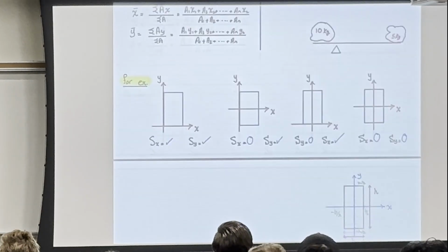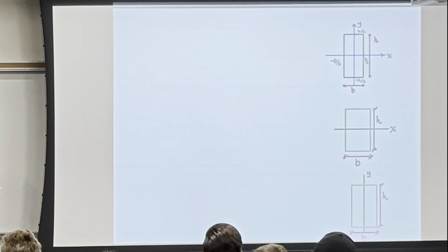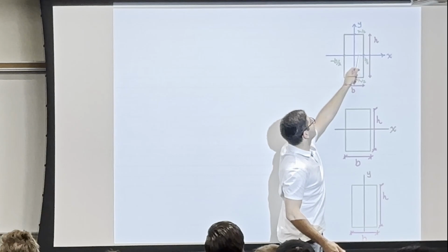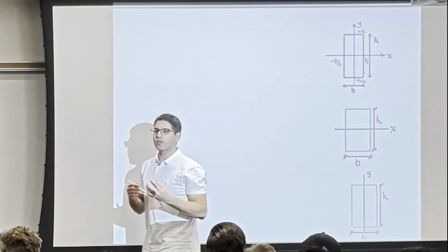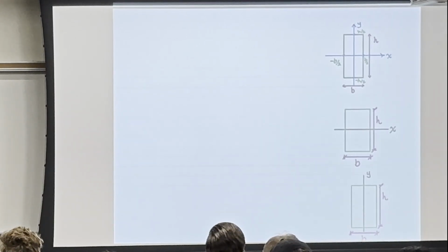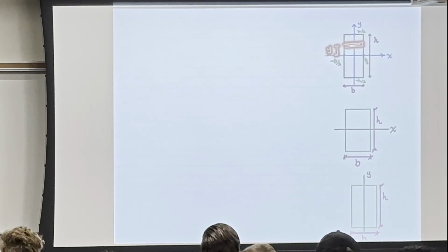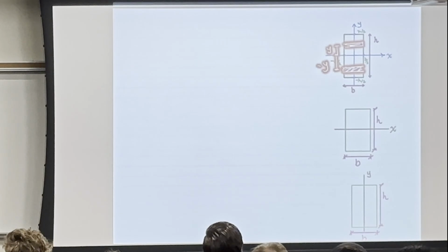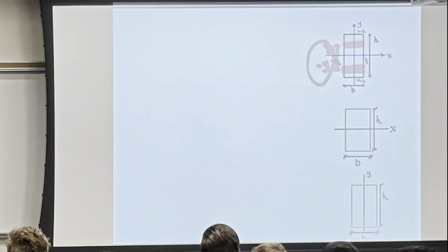And then we did an integration on one of these shapes, and we said we wanted to find the moment of area about, for example, the centroidal axis, and we found it's 0. The reason why it was 0 is because whatever strip we take here with a distance y, there was another strip here with a distance of negative y. That's why the first moment of area about the centroidal axis was equal to 0.